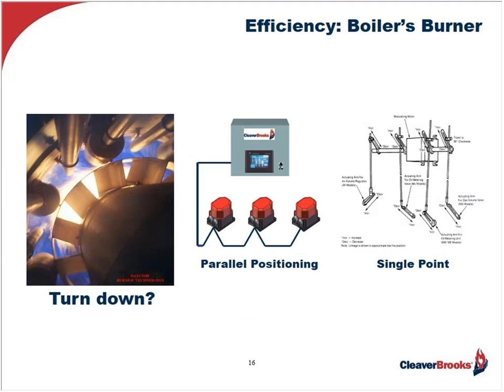Now, at the same time, the professional is taking note of climatic conditions. He or she is also paying close attention to the burner's combustion control system. If it's a single point or a parallel positioning system with independent actuators for fuel and air, this is the best control system as it mitigates hysteresis, slip, and wear, which is common with a single point system. But if the boiler doesn't modulate much and the linkages seem tight and in good condition, they'll note that too.